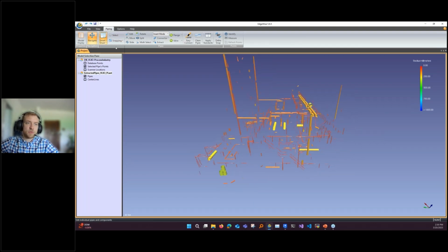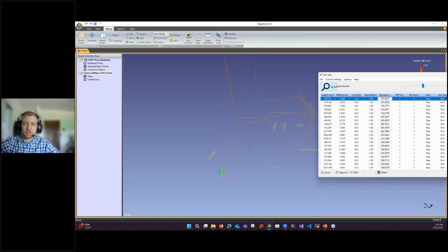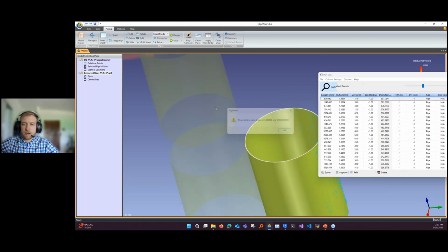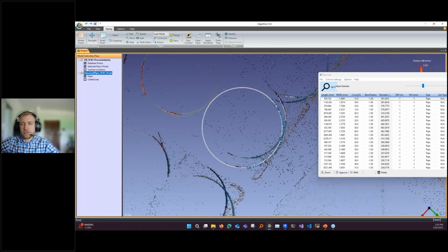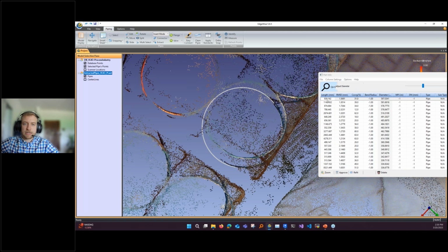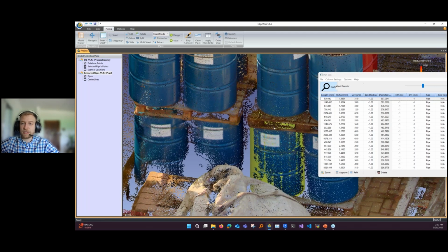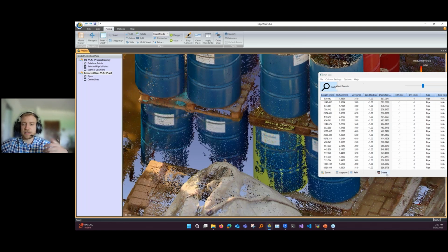The other QA tool that exists is our QA mode. If I click on this, it'll take me to a nice view of this element. I'm going to turn the point cloud back on, and we just see how things fit. Now, this one's a little tricky because stuff that is round is going to look really good here. Context is helpful. In this case, this is round. That's not what we want, so we're going to delete it.